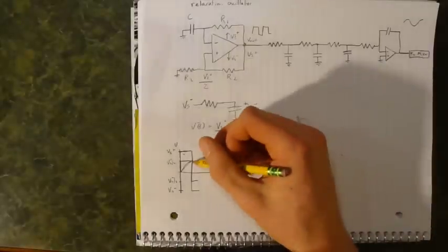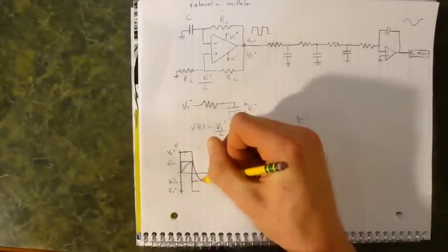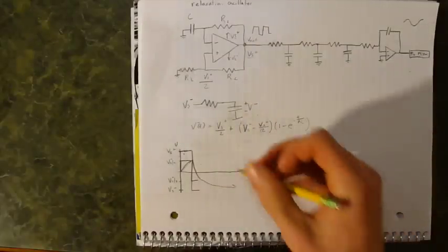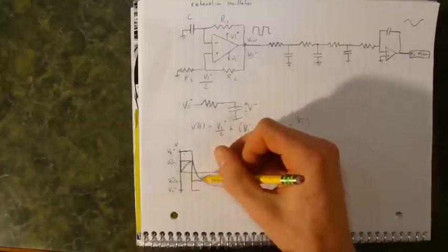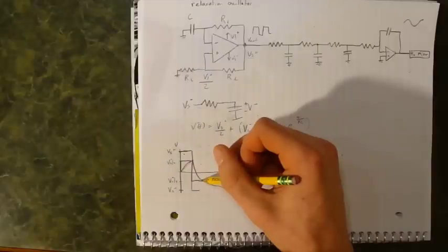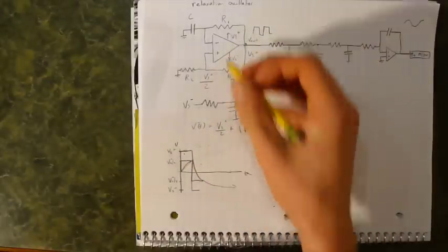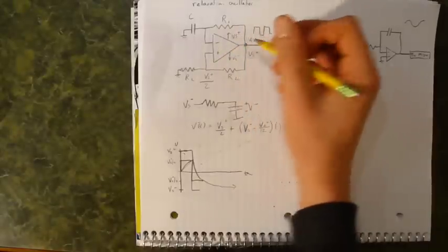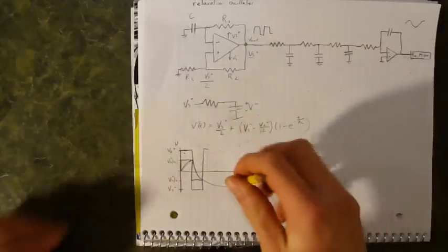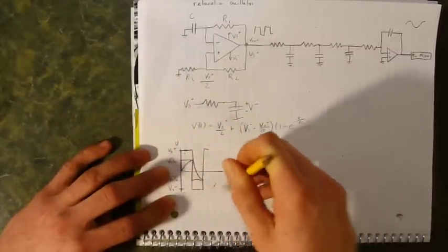So again, we can graph this, and it should look familiar. And it will want to look like this over the long run, but it does not, because once it equals the V positive pin again, the whole op-amp output inverts once more, and the capacitor stops charging again.